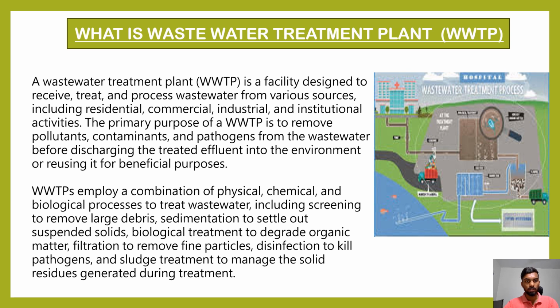Wastewater treatment plants employ a combination of physical, chemical and biological process to treat wastewater including screening to remove large debris, sedimentation to settle out suspended solids, biological treatment to degrade organic matter, filtration to remove fine particles, disinfection to kill pathogens and sludge treatment to manage the solid residues generated during treatment.